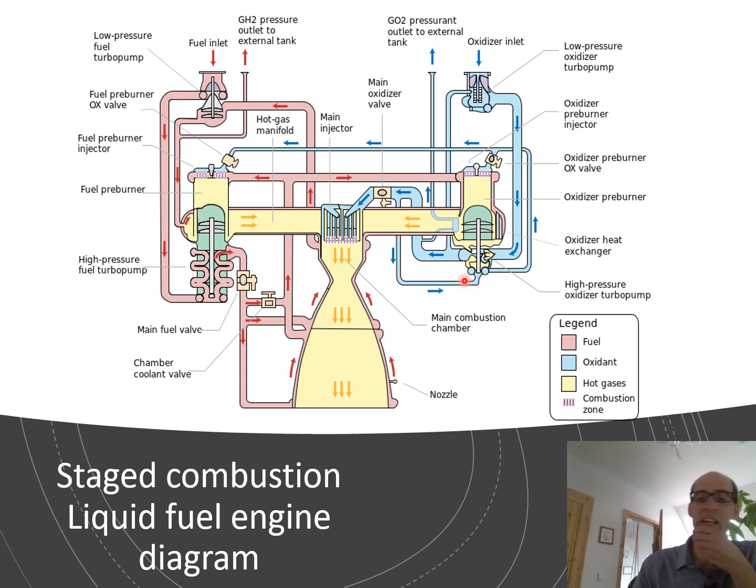Now, the pumps are needed to pump the fuel from the tank into the nozzle where the actual combustion takes place, because don't forget the pressure is very high when the combustion takes place, which means that the pumps have to pump the fuel in at a pressure that is much higher than the combustion chamber pressure. Otherwise the combustion would just work its way back up into the fuel tanks, and not to put too fine a point on it, kaboom.